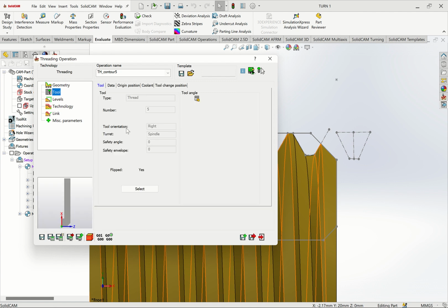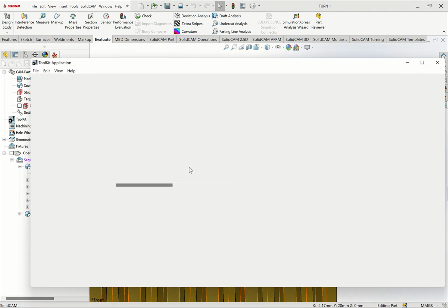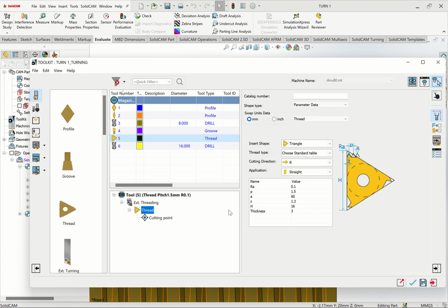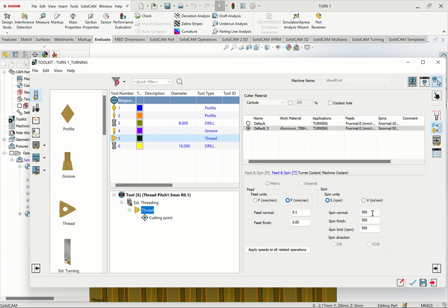That is one way. Then a tool, I also check the tool here. My tool, I'm using 16 ER, E meaning external right tool for threading with angle 60, pitch of 1.5. Then you ensure that you orient your tool to be along X axis, that is X positive, because the tool will be approaching from X positive, depending on your machine. Okay, then here some parameters are put.